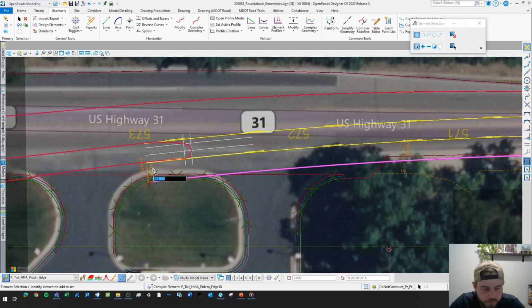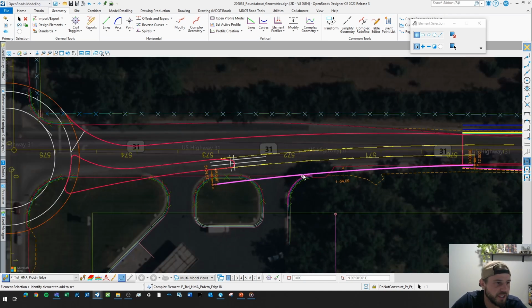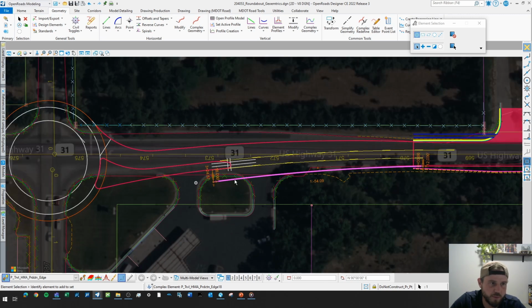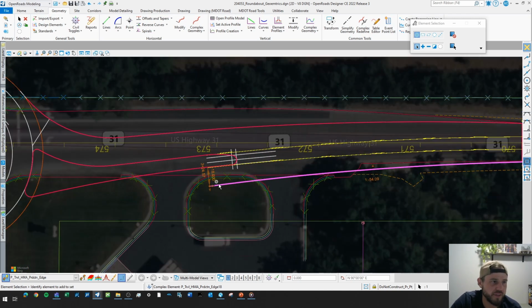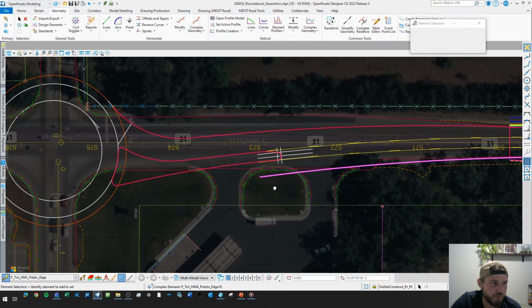Again, maybe I want to be at 18 feet, because I want to kill this lane probably as soon as I have the crossing. I want to be at 2 lanes up until the crossing, and then after that I want to taper as fast as possible. If not, you get people trying to speed past each other and things like that. So I could see this tapering down,